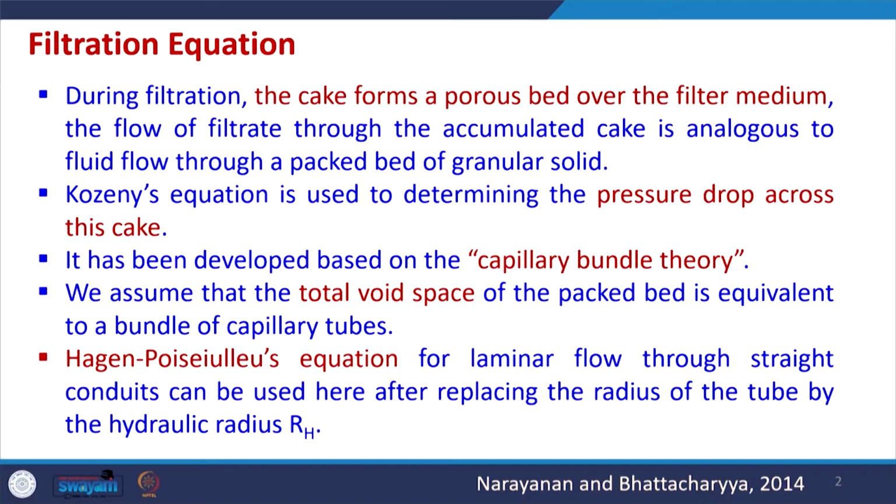This is the basic idea which is adopted in filtration. There are different equations which have been developed to determine the pressure drop across this cake, and those equations can be used for design as well. One of these equations is called Kozeny's equation, and it has been developed based on the assumption of capillary bundle theory. Here we assume that the total void space of the packed bed is equivalent to a bundle of capillary tubes.